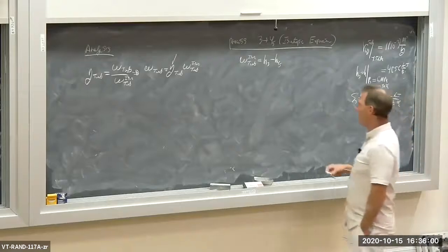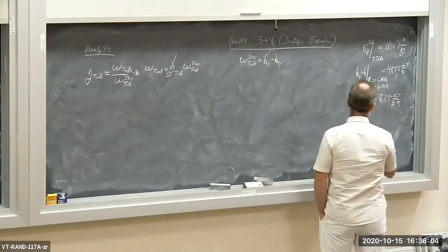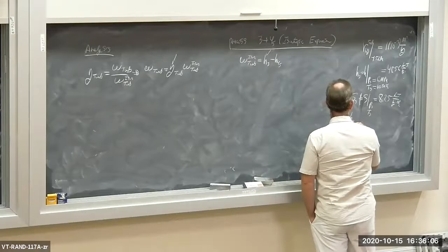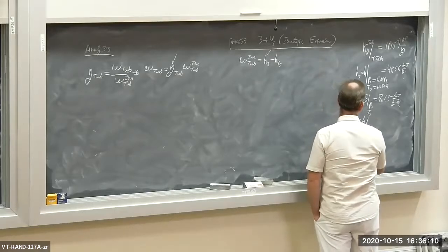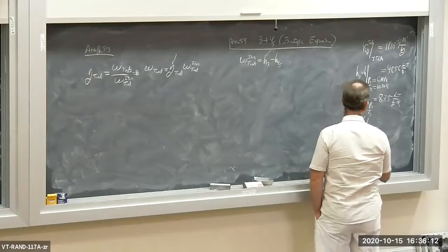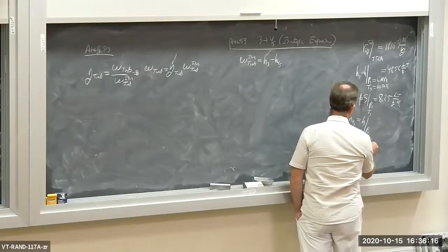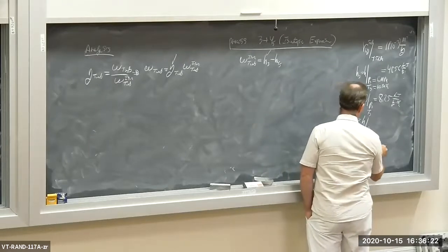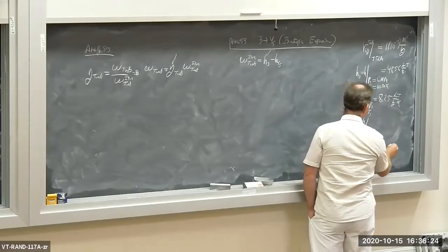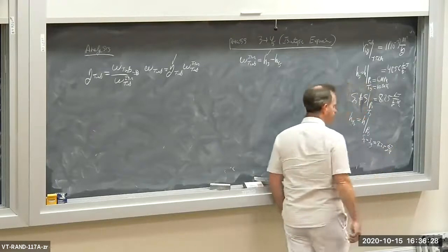Okay, so I have H3 now. So what's H4 sub S? H4 sub S is equal to H evaluated at pressure P4 and specific entropy S4 sub S equals S3. And S3, of course, is 8.25 kilojoules per kilogram degree Kelvin.